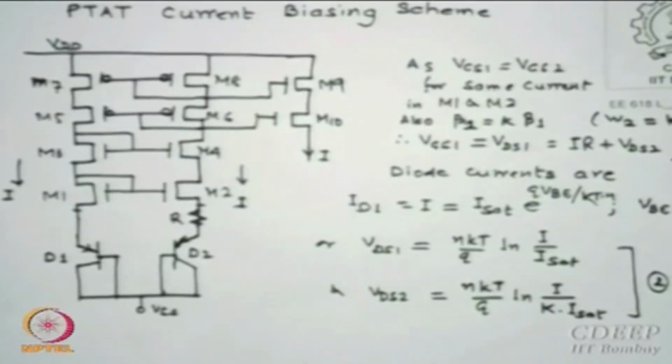Which one would be better? I can leave the collector open, or base emitter directly, or have base emitter and short the collector. There are three possibilities I can do. When do we take the base emitter junction and when the base collector junction? When I want a higher breakdown voltage, I use the base collector junction, as the collector has the lowest doping.